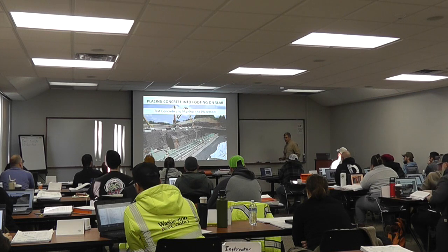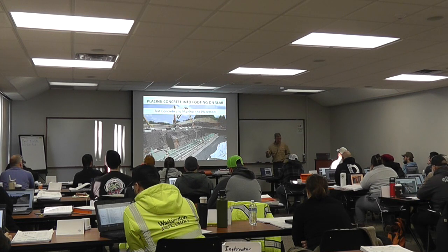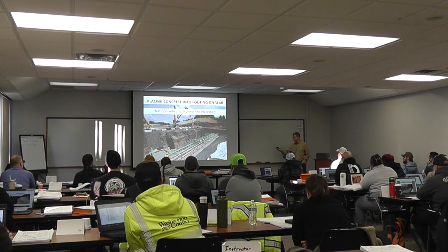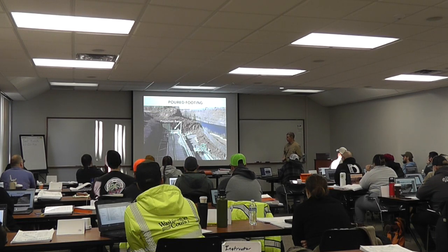So obviously there's going to be all the rest of the things that you guys as inspectors do, which is test the concrete. If there were any soil bearing tests, we could do them. This one obviously doesn't need it. But then test the concrete and monitor the placement.